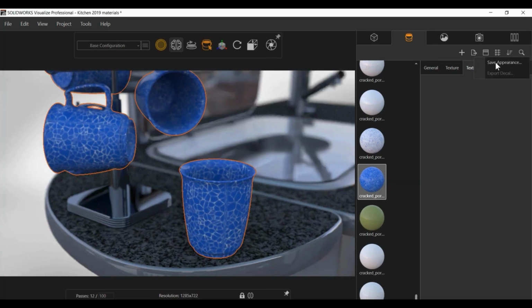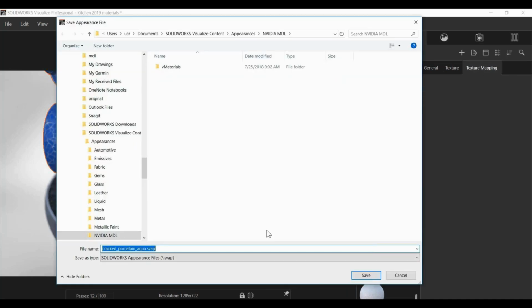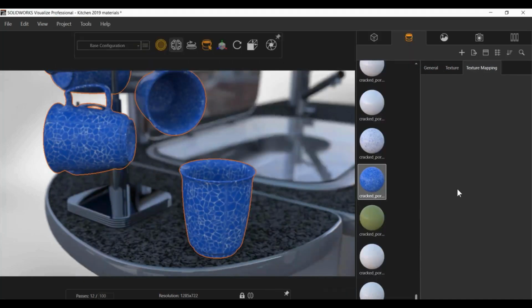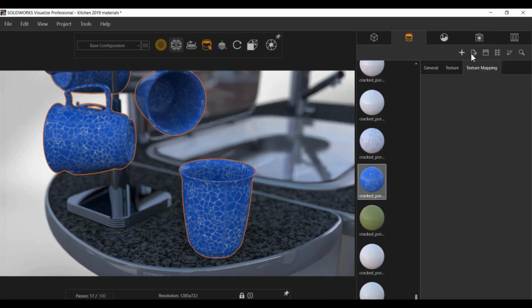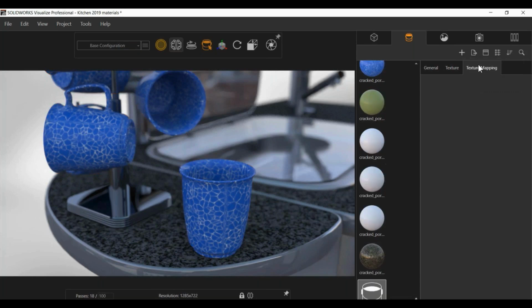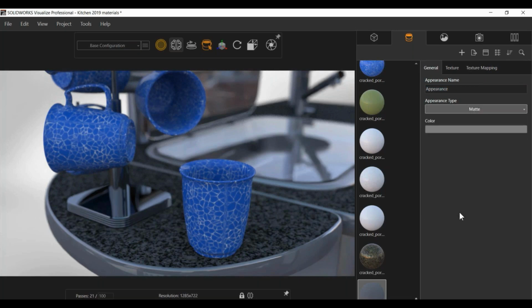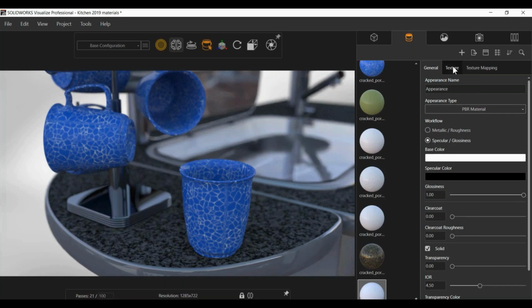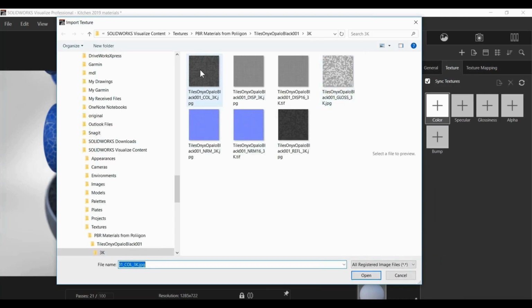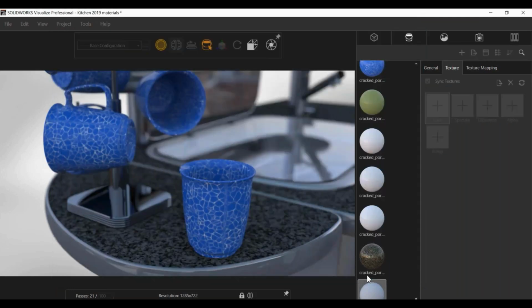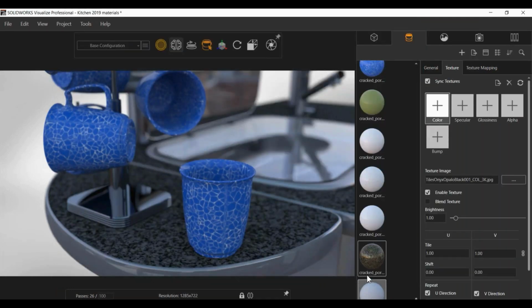And if you're making your own textures by defining some kind of textures and bump, you can also export that appearance for your future reference. Also you can share it with your colleagues. So here there are different types of appearance. As I told you, here we are talking about the colors, specularness, glossiness, alpha, and bump. So this many layers have been defined for your single texture.